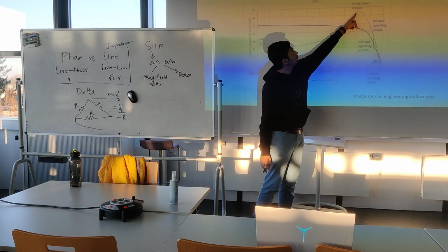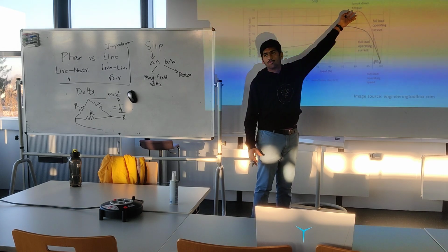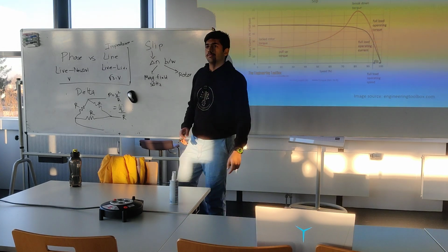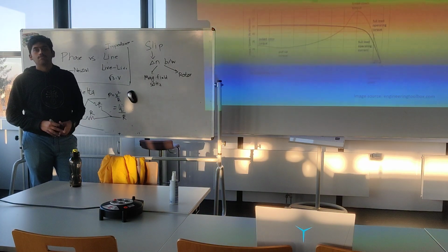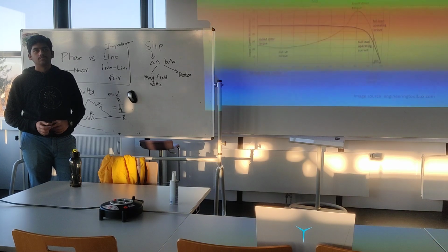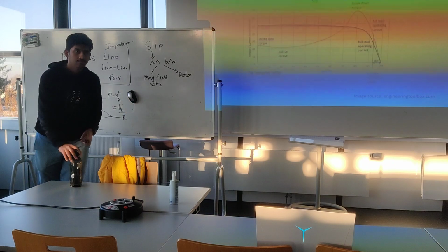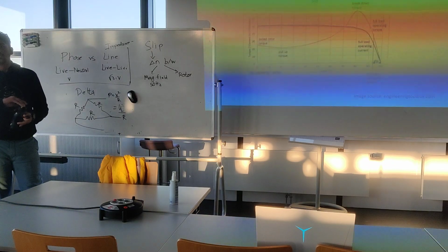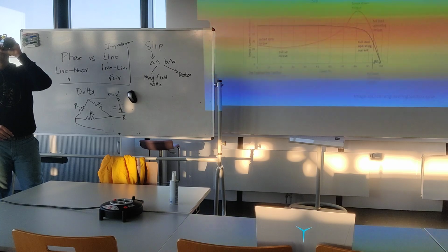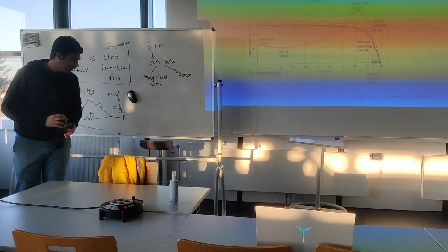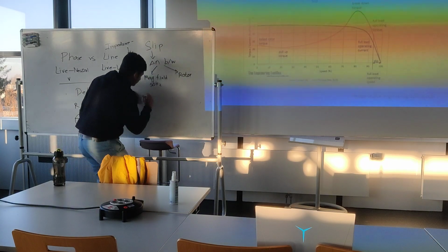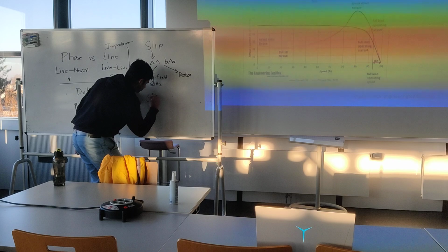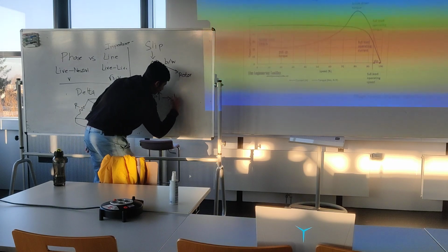But why do you think we don't use the breakdown torque point? Because it's giving more power, right? Why not go there? Maybe too much wear or unstable. No. It's not about mechanical wear. It's something on the electrical side. Heating. Heating, exactly. So as slip increases, you have more heat.